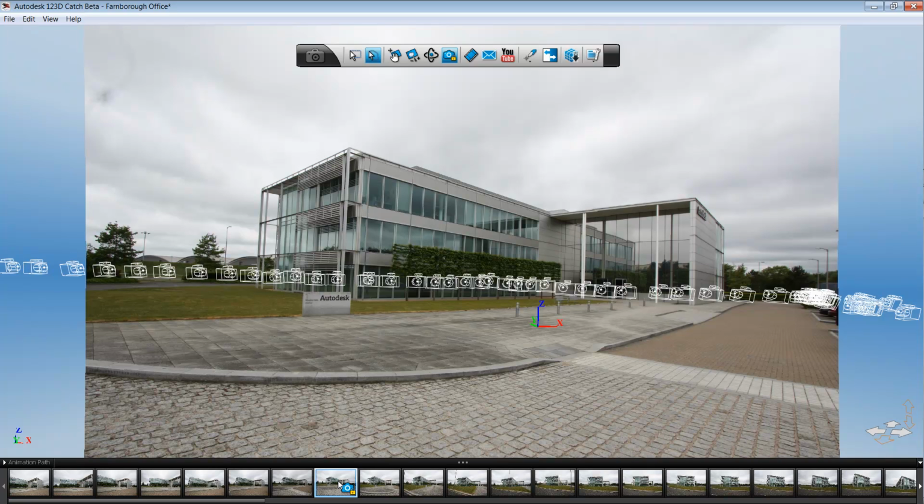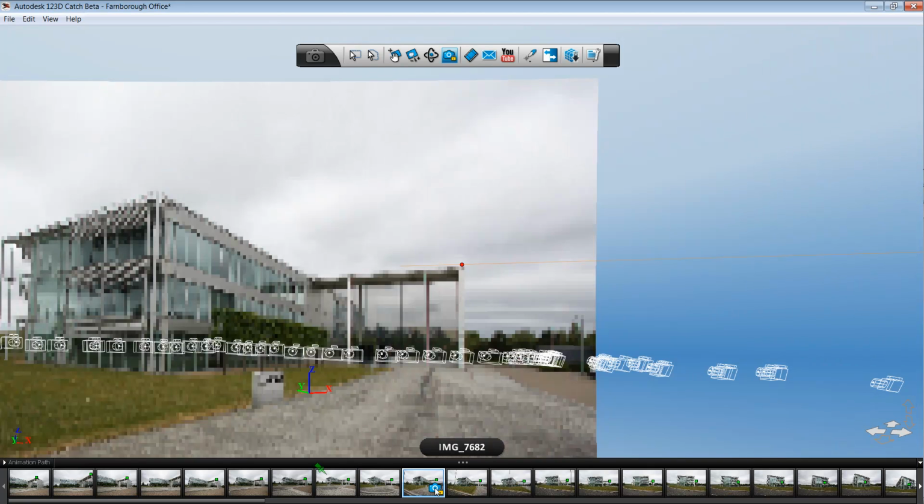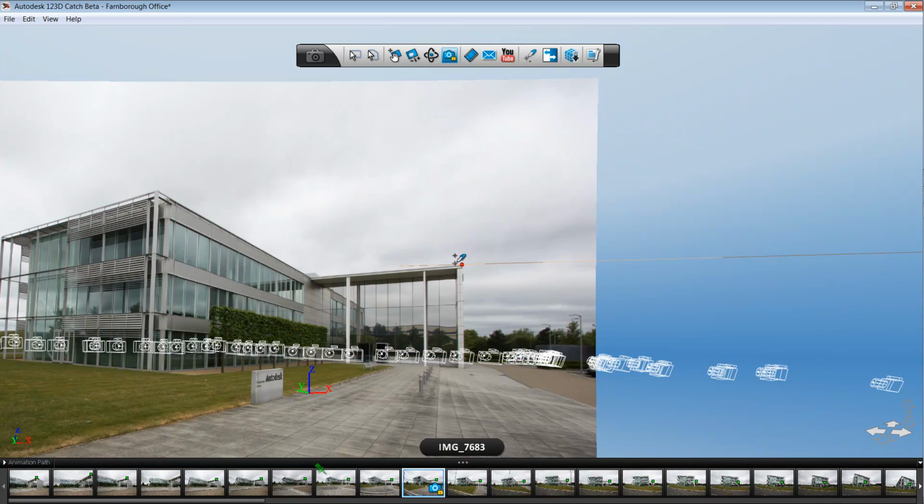So to start doing that, what we would do is first create reference points. So I've just enabled the reference point tool here. I can click inside the photograph and then place the reference point. You'll see that as I move around other photographs, the software has tried to place reference points in exactly the same place, so it's identifying common points, and you can move those if they're not quite right, or you just want to get them extremely accurately on there.